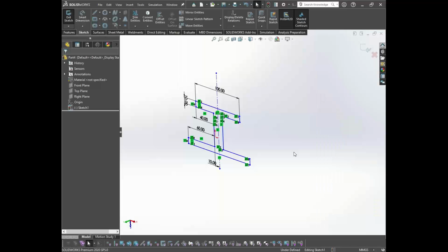Okay, that's good. Now, as I've shown in this session, apply a fixture on one side and apply a load of, let's say, 1000 newtons. Make it a compressive load. Don't apply the tensile load. Follow the steps that I have followed during the presentation.